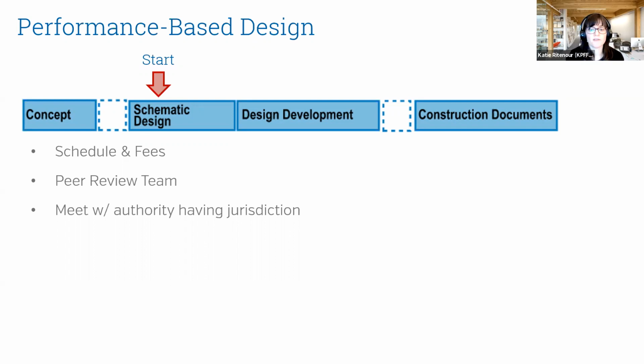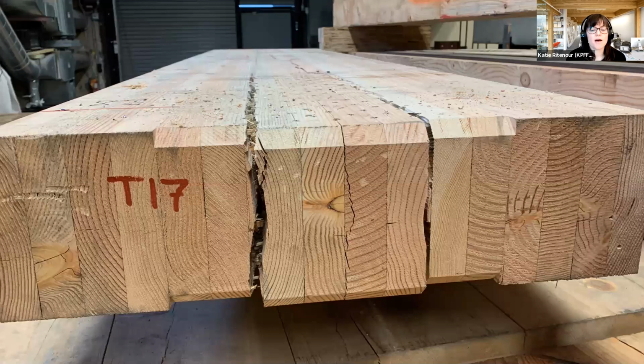You will need to evaluate if you need testing to be completed as part of the performance-based design. A lot of times with these new systems, you likely will need testing just because we're using the material in ways they have never been used before. Luckily for us, we have the Friends of the TallWood Design Institute to lean on and connect us with these researchers who can help us with the testing that we need for our projects. And then once we get in contact with those researchers, they will help us create the testing program and identify the cost for the testing programs.